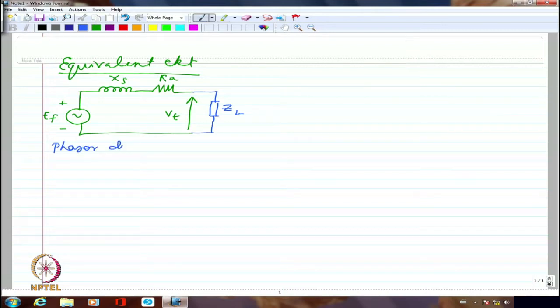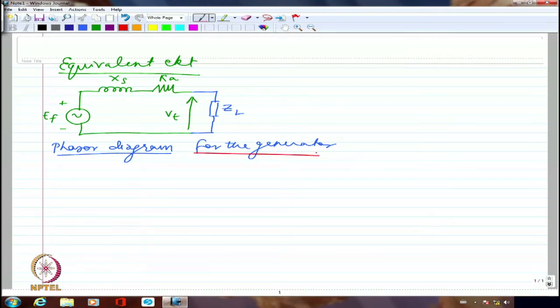So we drew the phasor diagram for the generator, which I want to specify once again. So this is going to be probably my EF. If I say IF is somewhere here, I should not specify this as IF, rather it is IF dash. So I'm going to have this as IF dash, which is the equivalent current on the AC side, which would have actually created a similar flux as that of what actually is the rotating flux of the rotor. The rotor is not having rotating flux electrically. It is because of physically rotating poles. So physically rotating poles creates a revolving magnetic field.